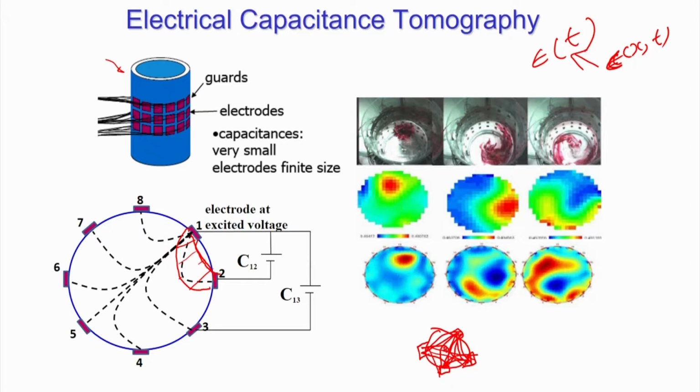You are covering the entire cross section, and because you are covering the entire cross section, you will get the epsilon as x and t. But the problem is your accuracy with the position is not very high, the spatial resolution is not very high. Please remember, once I say x, I actually mean x, y, z and t. Okay, so all the positions, because it is going to give you the 3-dimensional domain. So, all this you can measure, the temporal resolution will be very good, spatial resolution will not be that good. So, that is the limitation of this technique.